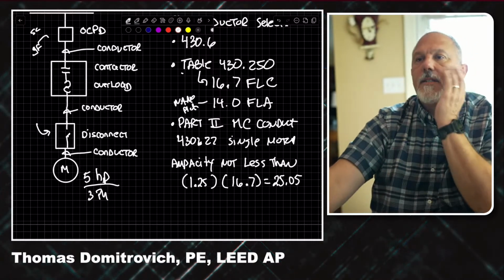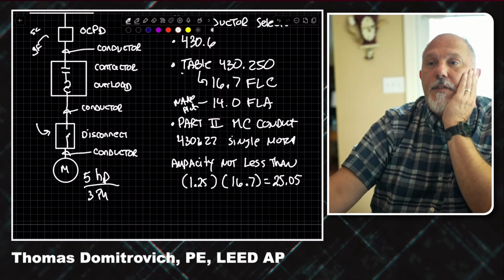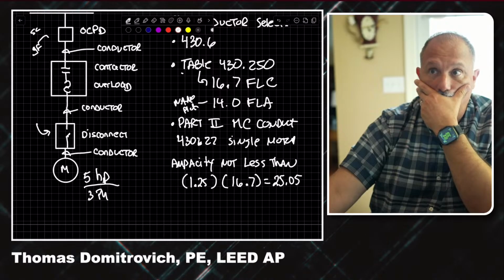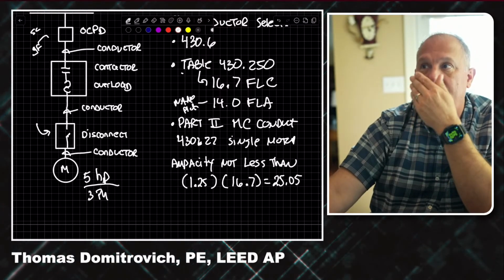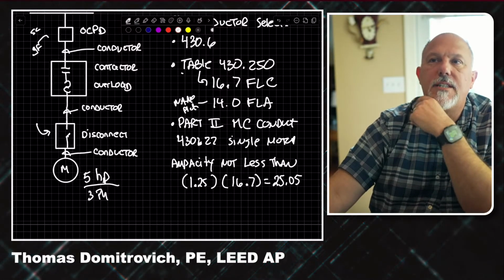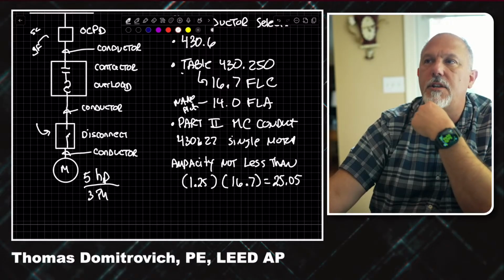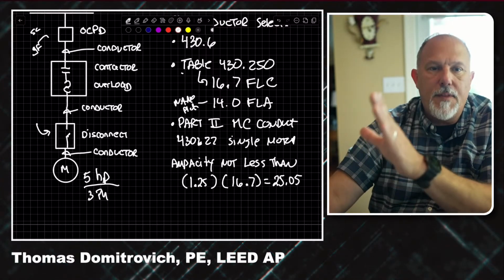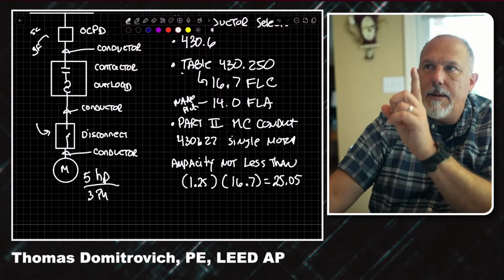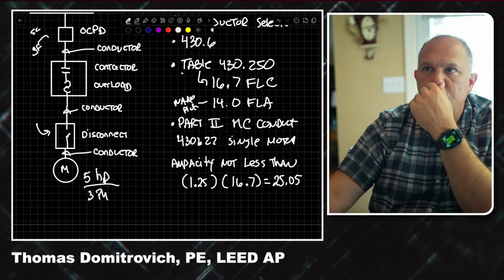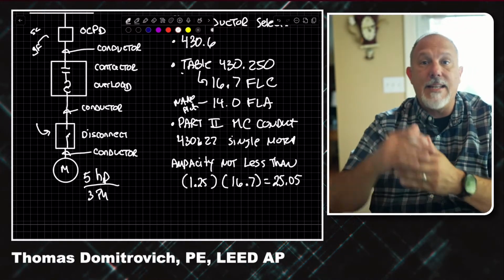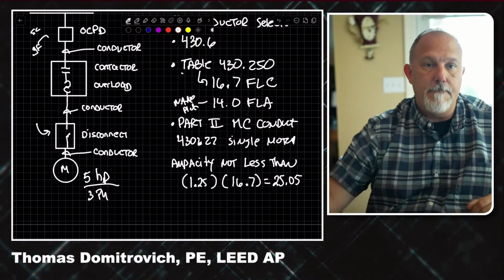I would feel better if it had a reference to 110.14, because 110.14 has nothing to do with ampacity. The conductor has to have an ampacity, but ampacity has nothing to do with the termination, 110.14.